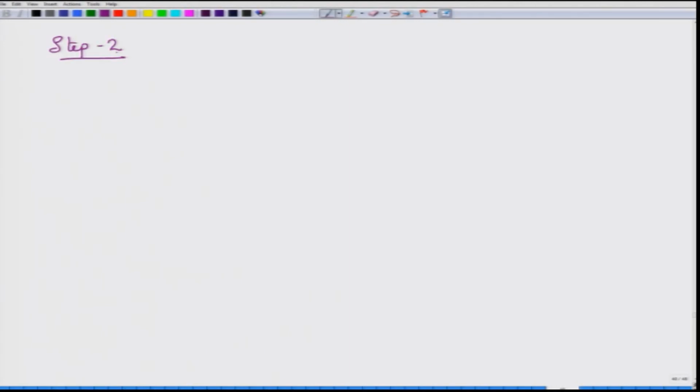Okay. So, this step should be familiar to you. You have two curl equations of Maxwell's that are important in this context. I am writing the Maxwell's equations in the region between the waveguides. That is the region where we have the waves propagating or the modes propagating, and outside the region it is not really of our concern at this point, but you can actually show that once you have perfect electric conducting walls, then those fields outside would not really be present.